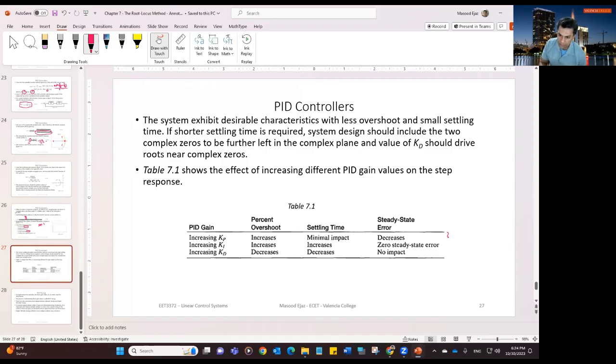The first two, P and I, control the steady state error. Together, they can create a zero steady state error. But the value of overshoot and transitions, that is how fast it should go to the settling time, can be controlled by changing the value of the derivative gain and adding it as a third block in addition to the proportional gain and the integral gain. So once again, this is a very common controller that is used even in digital control systems.